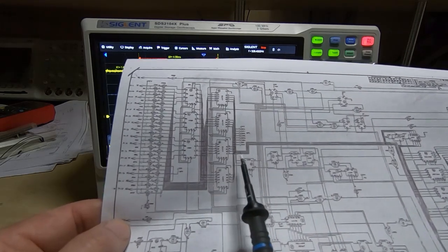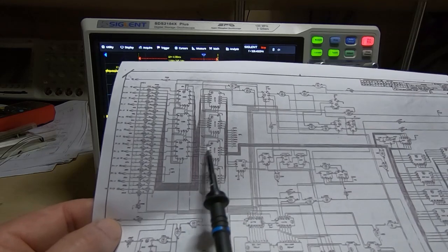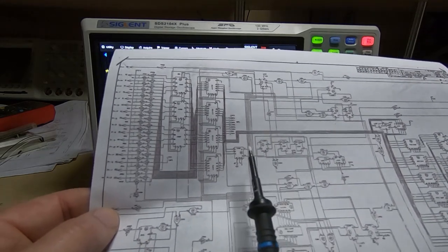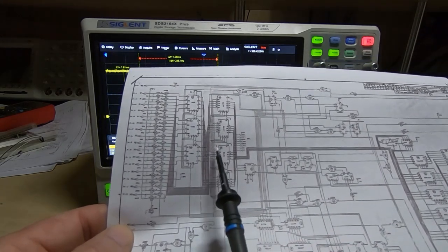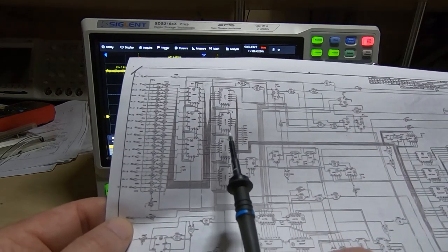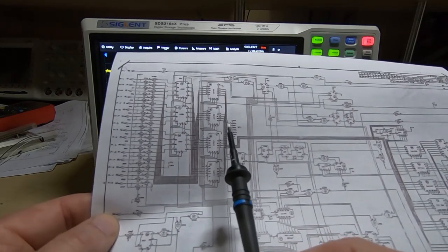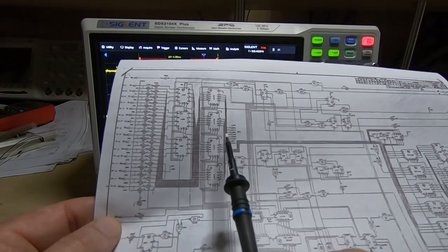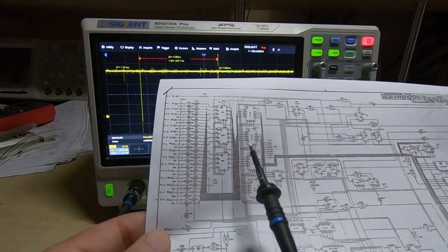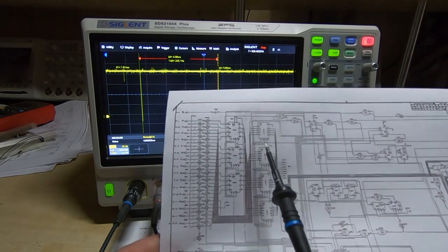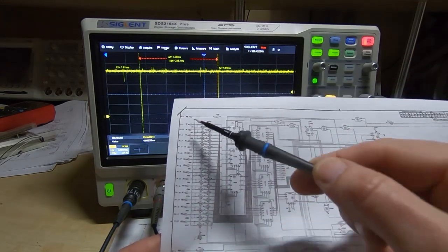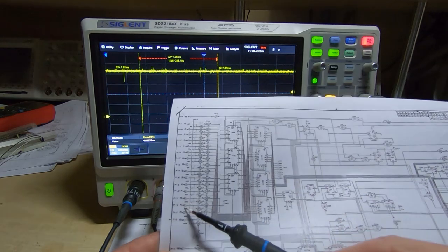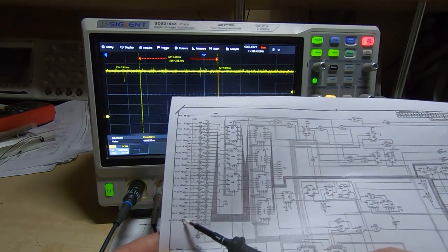I wouldn't normally do this, I'd normally move straight on and try replacing this device. But I'll attach the logic analyzer just to try and confirm, for the sake of the video, what I've been trying to describe. I'm not making it very clear here what is going on. But the logic analyzer will be connected to the PPU test connector, so it's effectively connected to these points for the address and data bus.